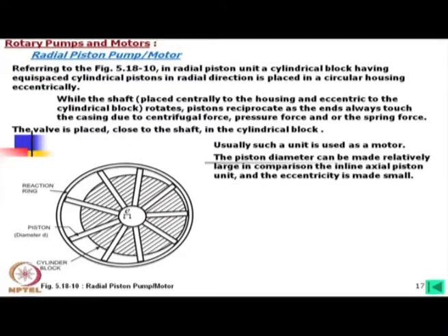In that case, say dP is 100 millimeter, so total length will be how much? Pi into 100 is about 314 millimeter. Now, we are going to use 7 pistons. So, 7 pistons means we need one hole and one space between the two holes.